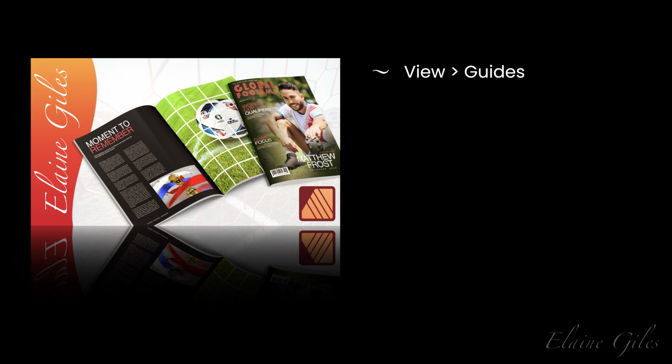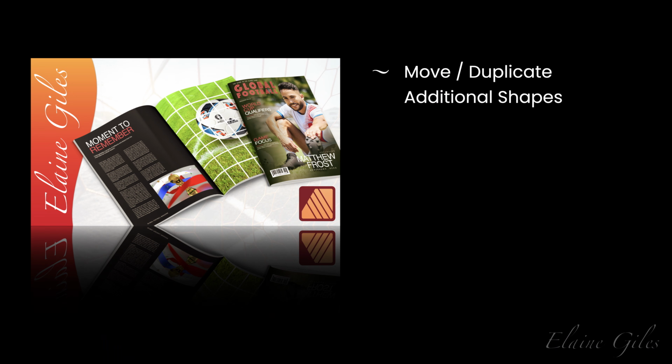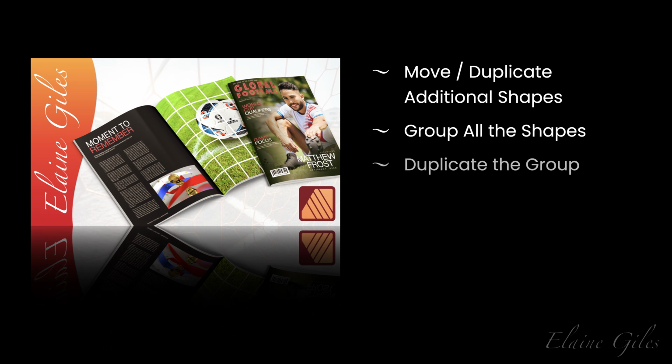I created a grid using view guides. Mine was on an A4 page with 5 columns and 7 rows, and I added 3mm gutters but no margins. I then added a single shape that was the size of one of those intersections. And I used Move Duplicate to create the additional shapes. I then grouped all of those shapes into a single group. I made a copy and hid it, ready to be used later.